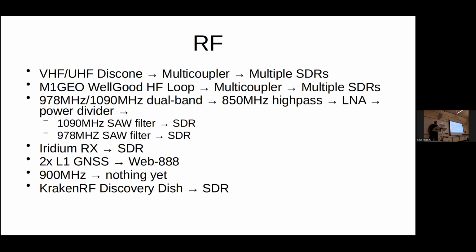The ones that I have are about $200 each. If you want to do this cheap, go and get a cable TV drop amp. They're like $40. Look for ones that are unity gain or 0 dB gain, and they'll do exactly the same thing. It doesn't matter that it's 75 ohms instead of 50. When you're doing just receive, it works just fine. I went this way because I could.